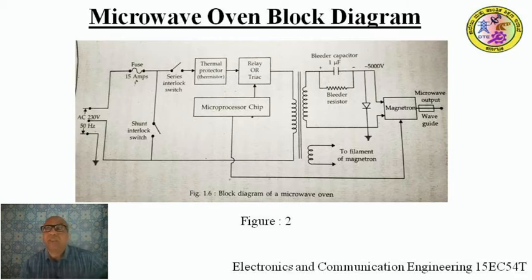and then you can see the interlock switches are linked with the oven door. Power will be applied to the mains transformer only when the oven door is closed. This is for the safety of the human being or the man who is using this oven. An interlock switch in series with the transformer primary. Hence, even a spot of dirt in the relay can't turn the oven on when the door is open.